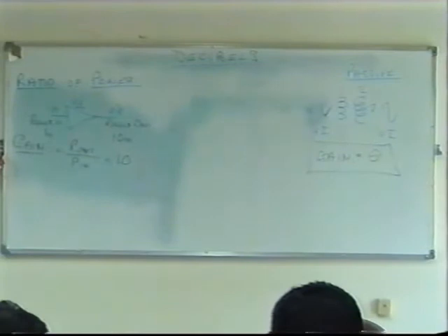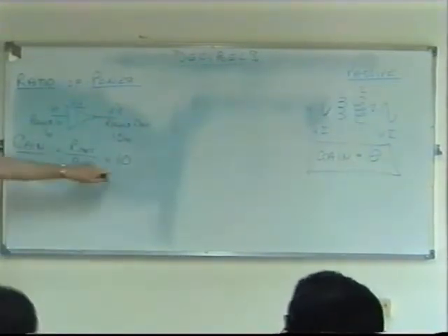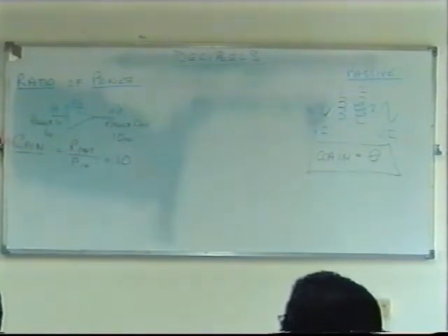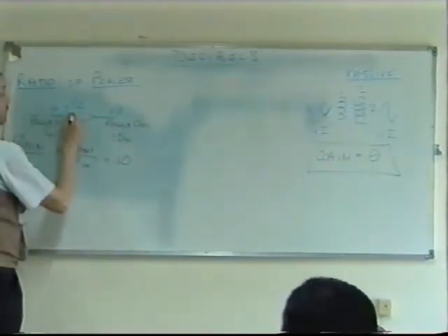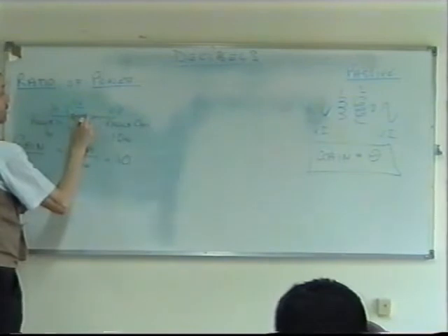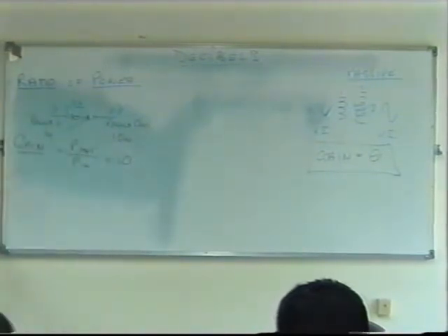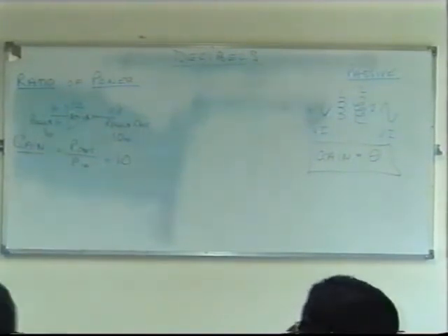Where does that extra power come from? How can I get more power out than I put in? From the power amplifier. Yeah, from the DC power supply to the amplifier, yes. So we can't get something for nothing. That's where it's actually coming from. In other words, we must have here an active component of some description. Active meaning it's going to change that DC power into the signal power that we want. And that's when we talk about gain.